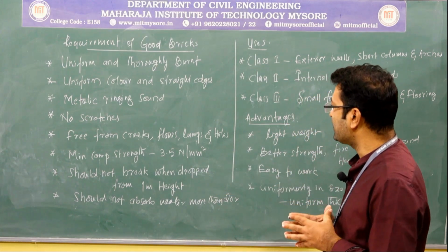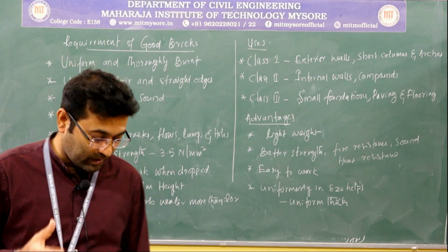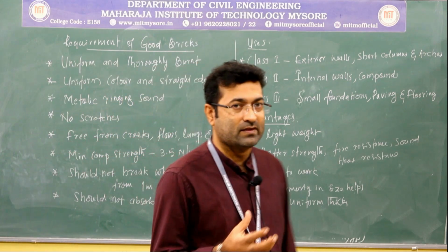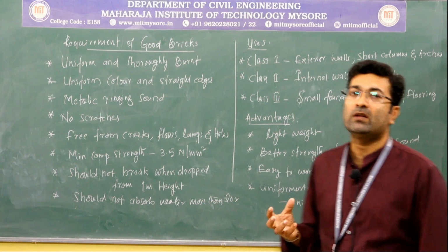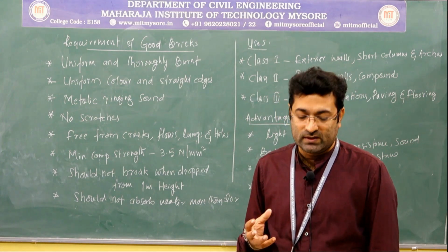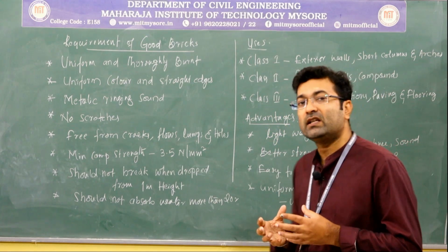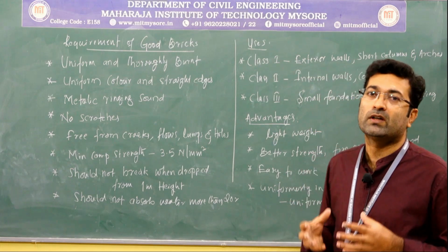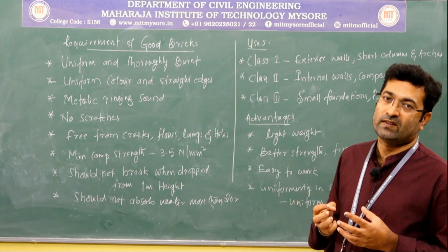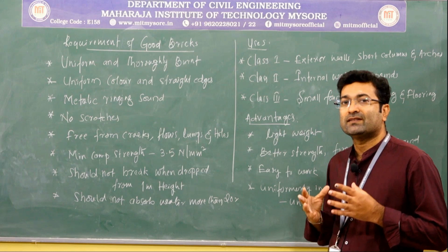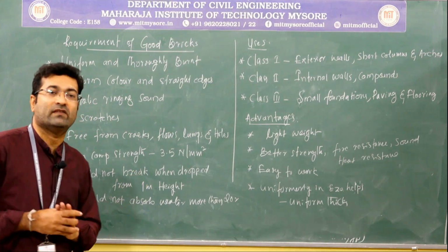Then the next one is when we immerse the brick in water for 24 hours, it should not absorb water more than 20% of its weight. Whenever bricks absorb more than 20% water, it clearly indicates that the bricks are not burnt properly. They have many holes inside which absorb the water. Whenever bricks absorb more water, their strength is usually less. So, it is not a good quality of bricks.